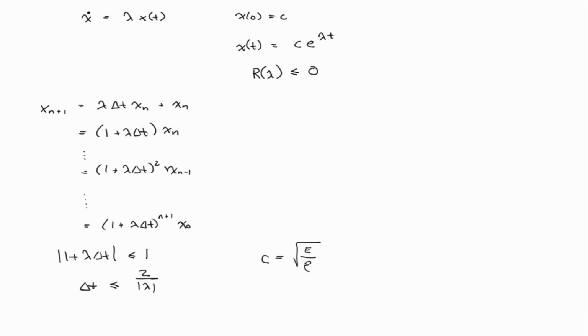So it turns out your delta t, your stable time step for that scenario, is something like 1e-7 or 1e-8 seconds, right? And you want to do a drilling simulation that lasts 60 days. Good luck. Taking steps of 1e-7, not going to get very far.